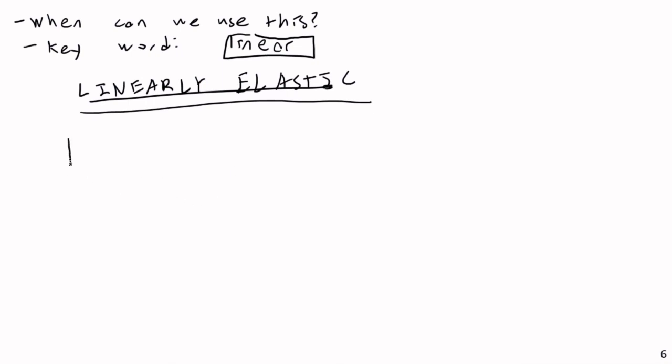So, again, if I go back to my good old stress-strain diagram, if I have strain and stress, we know that the stress-strain relationship generally follows a curve, kind of like this. We start out linear, and then eventually we top out, and then we go into yielding. And we usually approximate it like this.